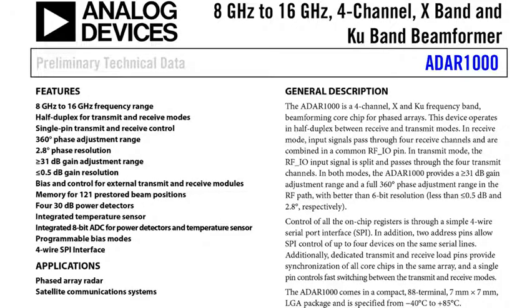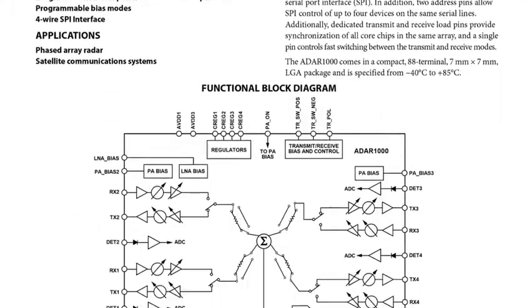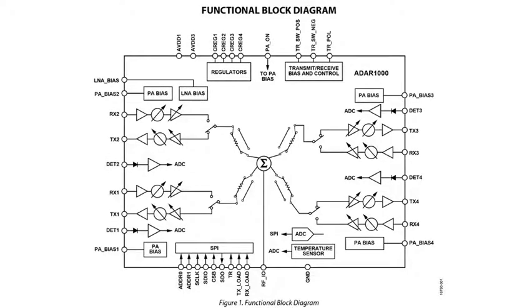In addition to the 4 vector modulator channels, the ADAR1000 IC also includes on-chip DACs for LNA and PA bias, along with fast TR switch control outputs and a number of other valuable auxiliary functions. ADAR1000 is in mass production now.